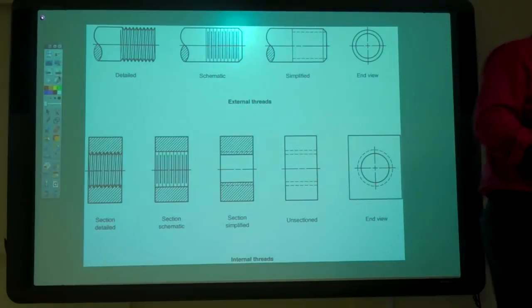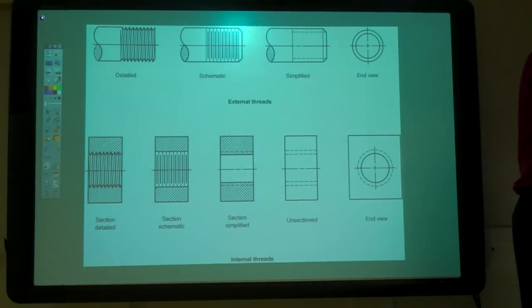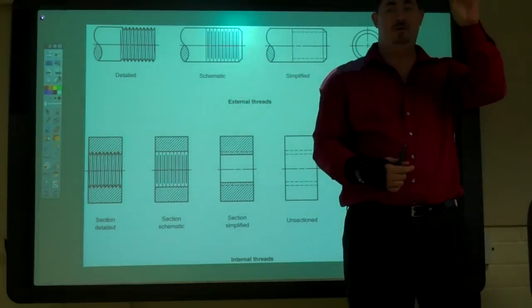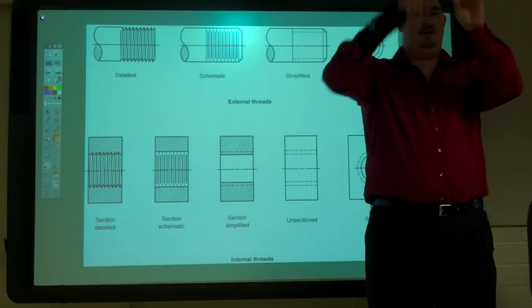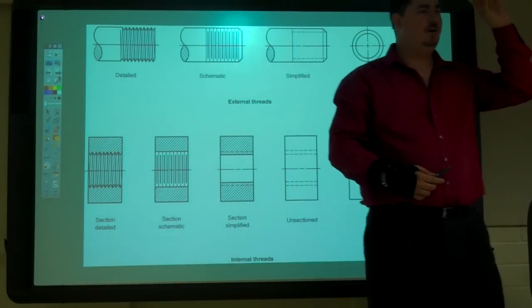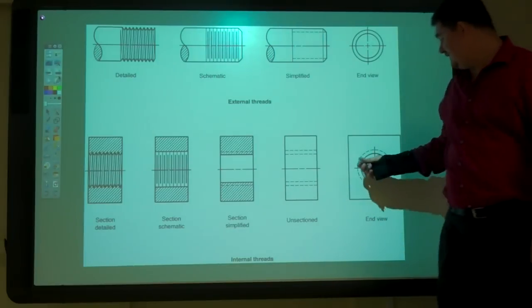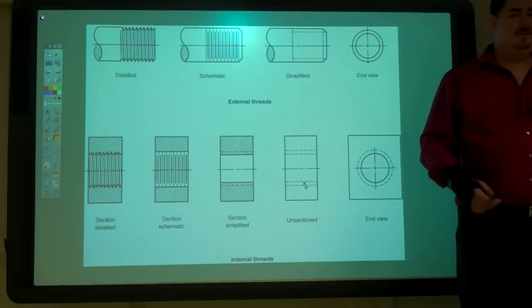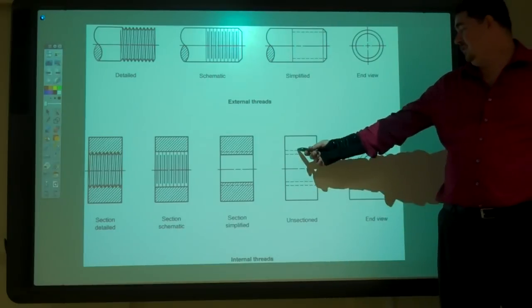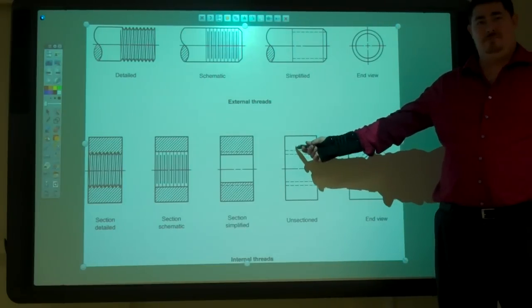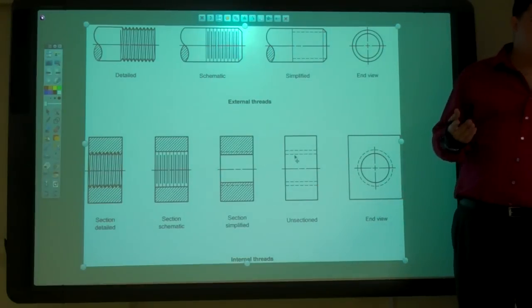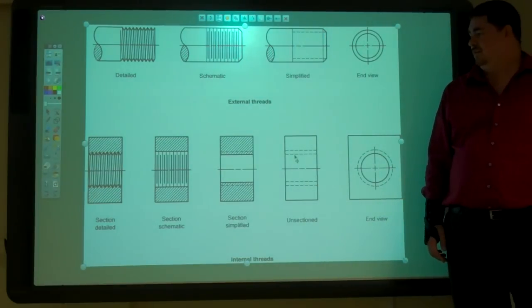So if you're looking through it, you're seeing right through the minor diameter. The major diameter is kind of up in there, hidden. You can't see it, so that's why. So if you ever see this, you know that, okay, that's a screw. Two parallel hidden lines grouped like that, probably going to be a screw of some kind.